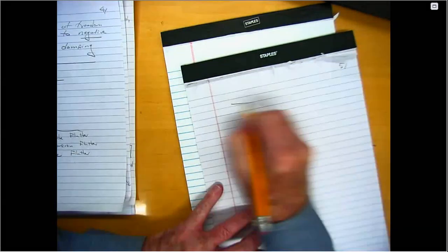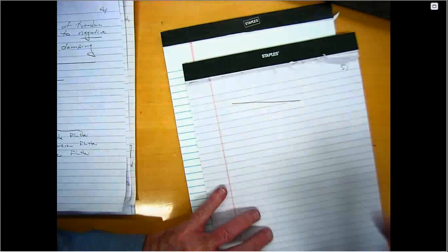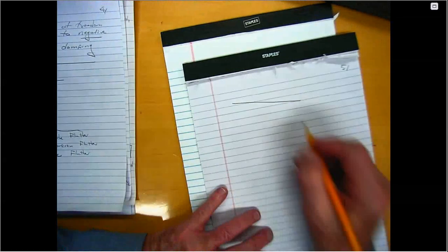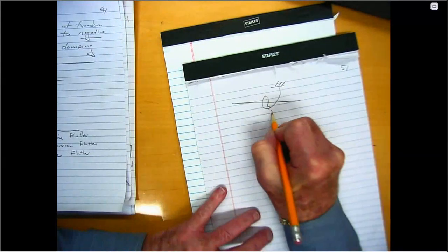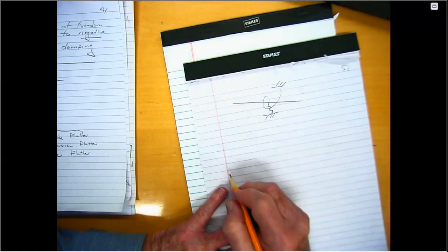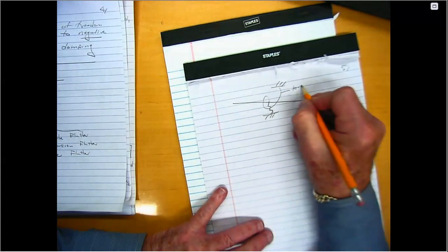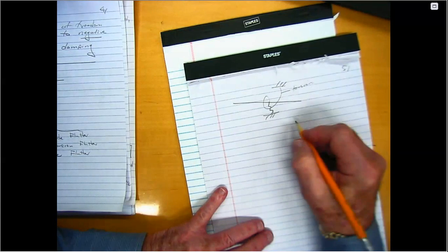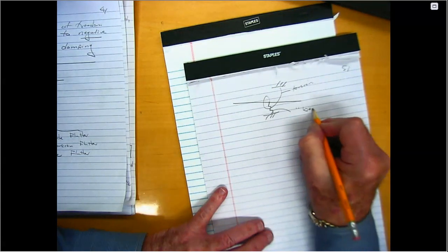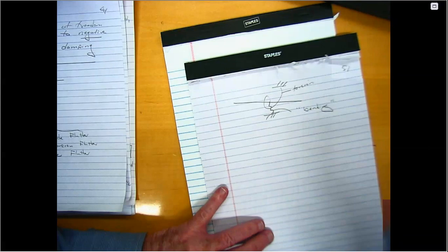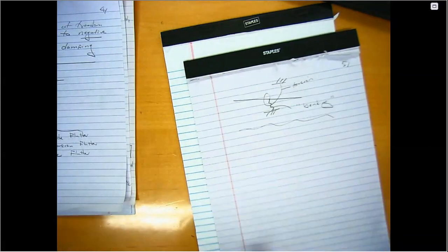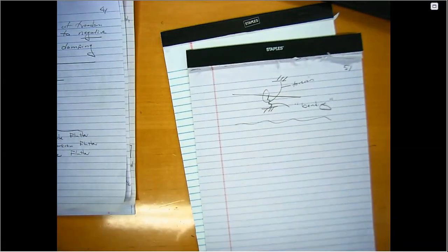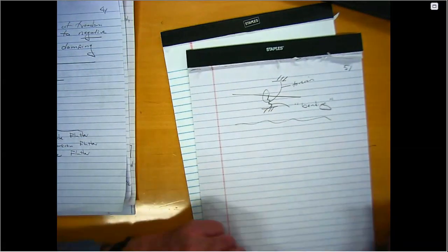The classical example, this is in the book, which I'm not going to discuss since you can do it in the book, is I have my torsional spring again, but now at the same point, I put a translational spring. So this represents torsion, if you will, or twisting. And this represents, I'll put in parentheses, bending. It's really translation on the spring. So you can develop the equations of motion for that case, and I'll let you read about it in the book. And we will move right along and do the wing case straight up, right?